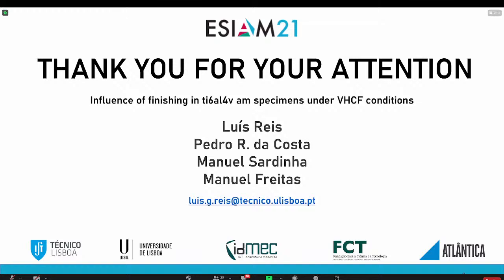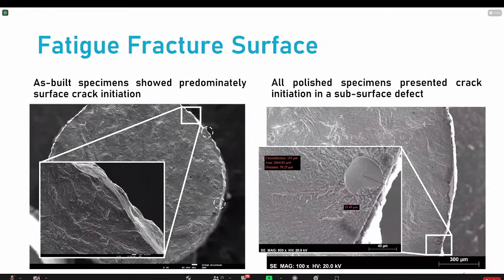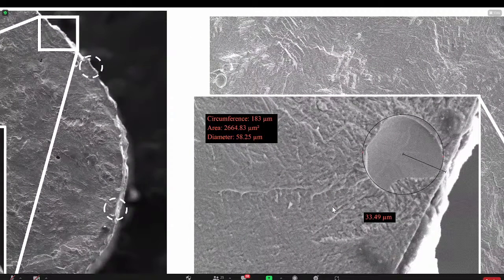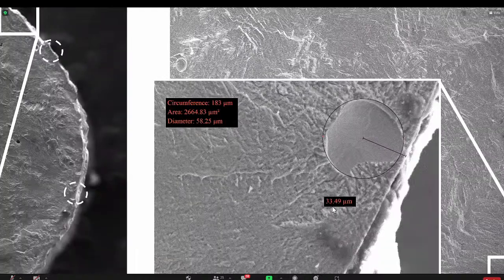Not all steels have shown very high cycle fatigue, but crack initiation tends to start at defects, where we can see first what we have called the fine granular area. We can see, for example, here on the right, I can actually zoom in. Perfect. This area is associated with very high cycle fatigue. This is one easy way to identify this sort of crack propagation and initiation in very high cycle fatigue.